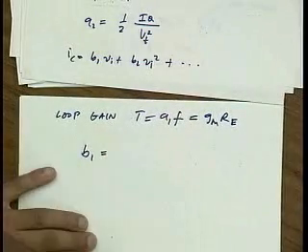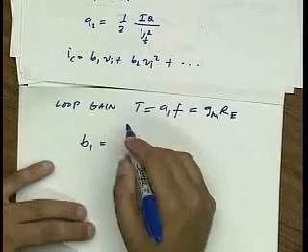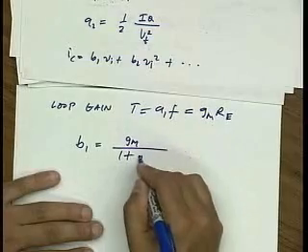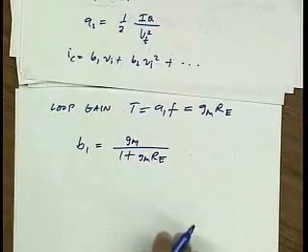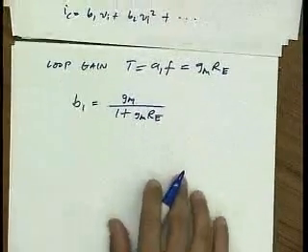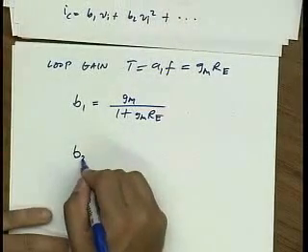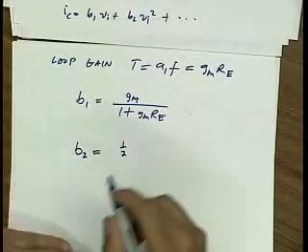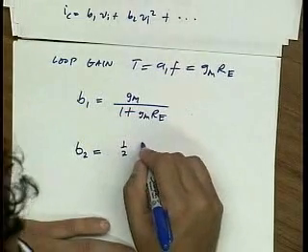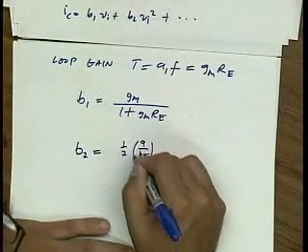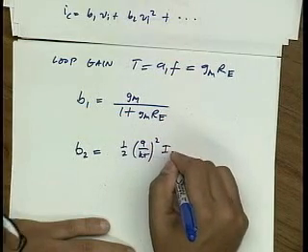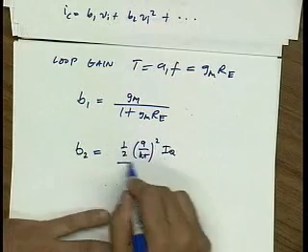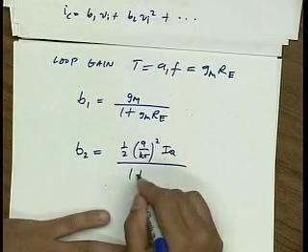So my B1 coefficient is A1, which is GM, divided by 1 plus T, which is 1 plus GM-RE. Now that's a no-brainer. We knew that from linear analysis. But what's more interesting is B2. B2, remember, is A2, which is basically IQ divided by VT squared, or multiplied by Q over KT squared, divided by 1 plus loop gain cubed.